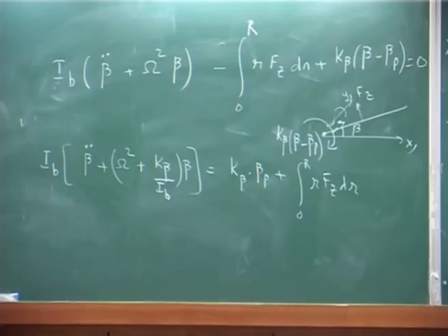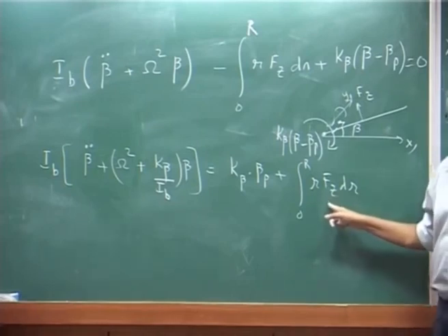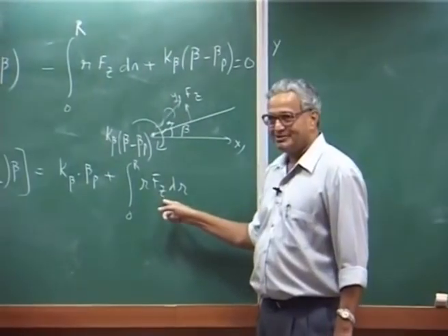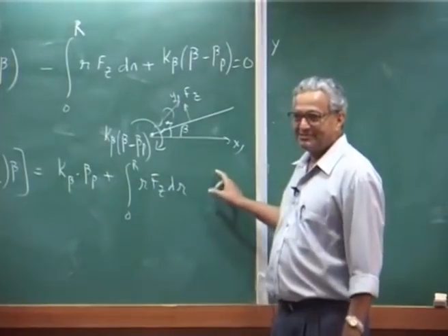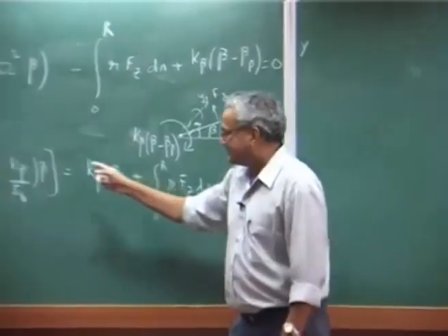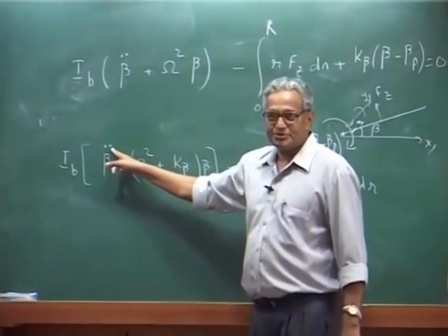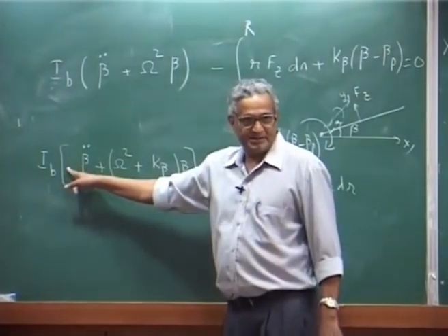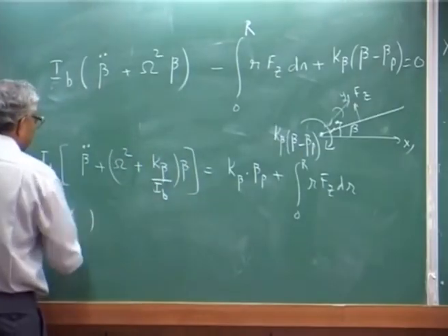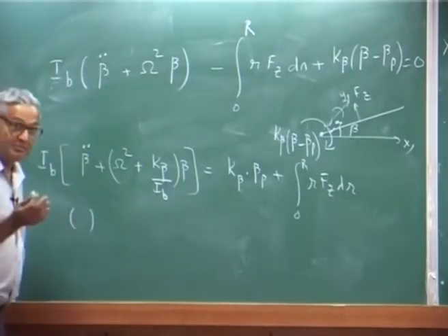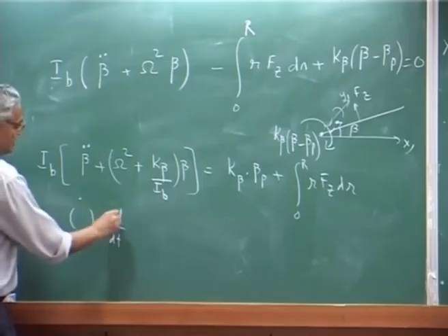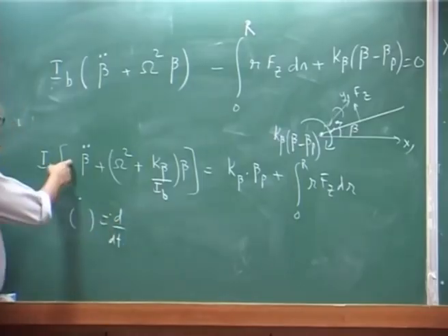Only thing is you have to substitute for, I am not writing the entire thing, substitute for F_z, which we know earlier, that is the lift force, lift per unit span, put that value and expand all the terms, multiply and then divide by this dot, convert it into non-dimensional time derivative. So you will get an omega square, okay. So this I can convert it non-dimensional, because this dot is d by dt. So I put an omega, denominator another omega, so I will get an omega square.